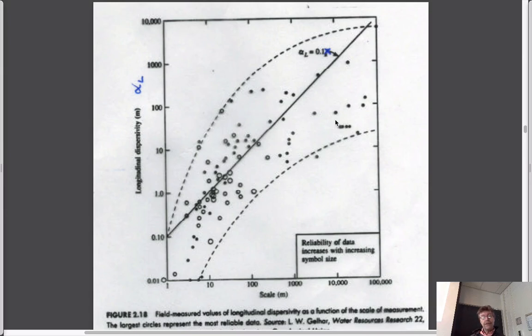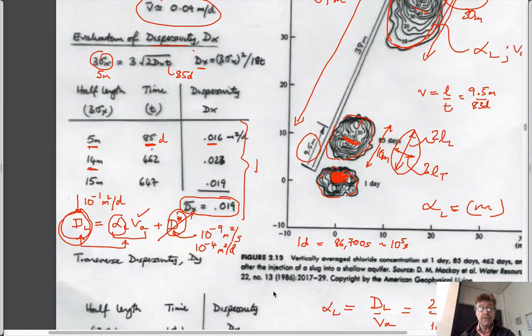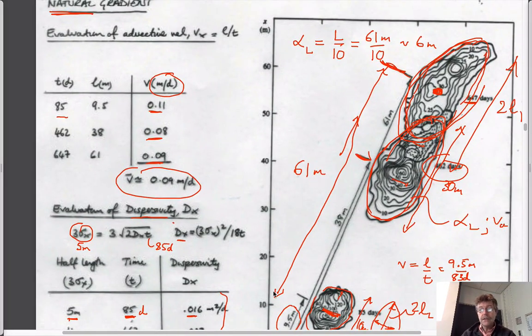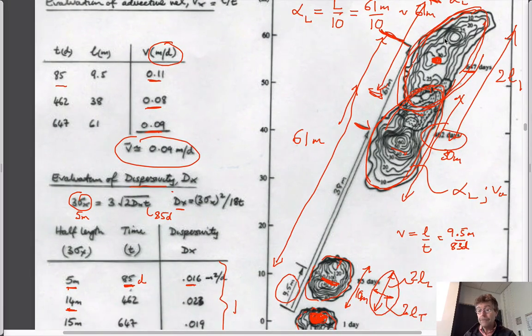If you do that, then for every single plume, you could measure, from the size of the plume, you could calculate what this dispersion coefficient alpha L would be. And you could also measure how big the plume was itself. This term here, the length of the plume. Actually, the two parameters that describe this, right? So this is the length of the plume, right here, if you like. And alpha L would be the number that you applied to be able to get from that.